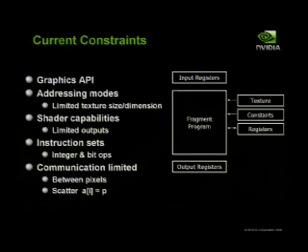You also were missing bit ops, so you were missing all the fundamentals of a CPU instruction set. This further got complicated by addressing modes because you had to do all of your addressing in floating point space. So imagine trying to compute addresses into an image or into a memory, and then you realize once you got to a certain size, floating point numbers start to skip integer numbers. So there's certain spaces of your memory you just couldn't address.